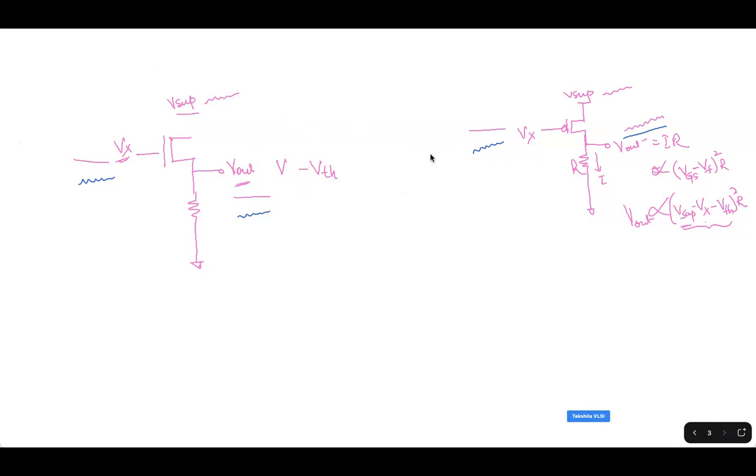I was discussing when we will have better power supply rejection, especially considering the PMOS and NMOS drivers. What should be the noise at Vx, or the input to the driver? Should it be noiseless, or should it also have some noise? That's the question that we have currently.